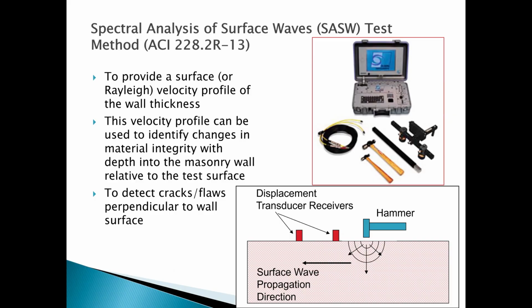Basically, we've applied it to pavements and structures as well as the first application. It was kind of the forerunner of what Choon Park at the Kansas Geological Survey did for multi-channel analysis of surface waves, which we also do a lot of on the geophysical side of things that we do on projects. So the basic idea is you have two receivers, you impact the material, and you watch how the surface wave, the Rayleigh wave, propagates between them, and you measure that vertical component.